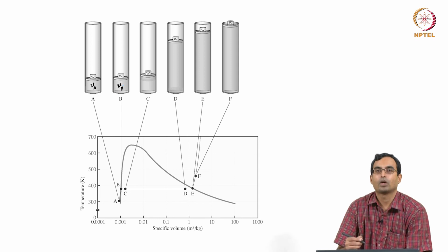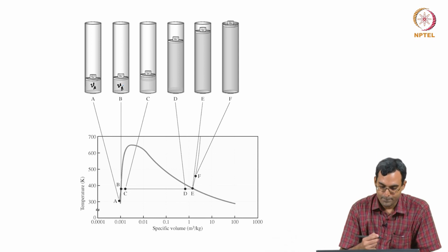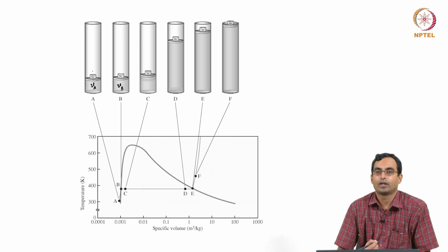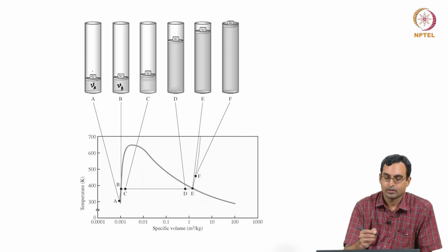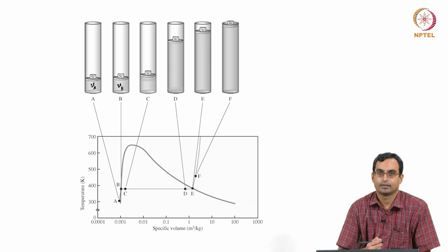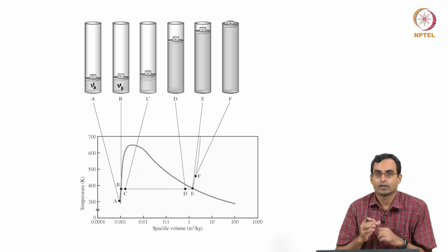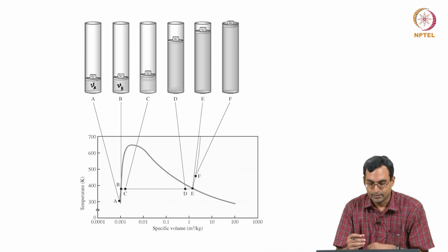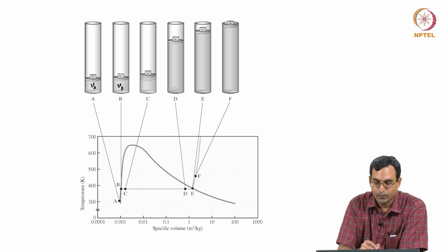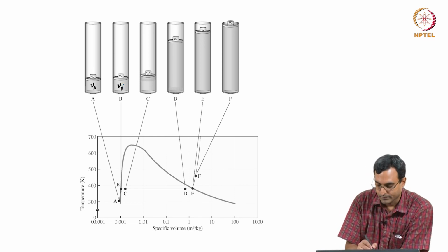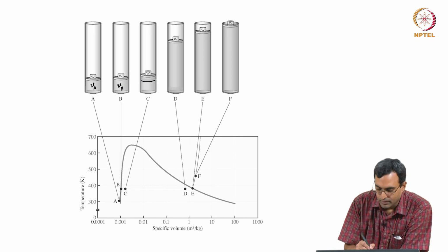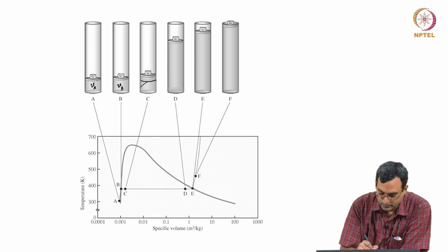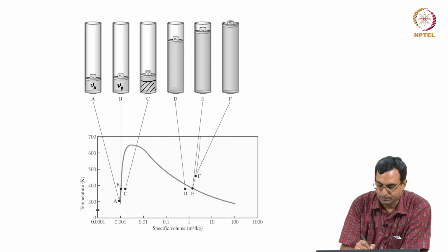we reach at some point the boiling point of water at this given pressure. If this pressure was say 1 atmosphere, then the boiling point would be 100 degrees or close to it. So, let us say at B we have now reached 100 degrees. So, we now have liquid water, all of which is at 100 degrees, it is ready to become vapor. So, if we give it some more heat, what happens is that this liquid starts to boil and become water vapor or steam. So, if we continue to heat it after a while, we have here liquid water, and on top of it we have some amount of steam.